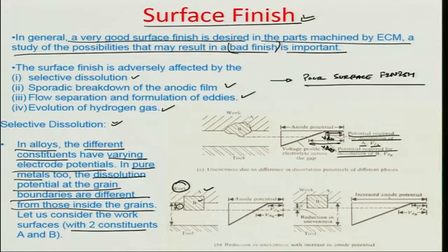So, we would like to presume here that there is an ohmic drop in the electrolyte in between this gap. This is all filled by electrolyte, and there is a straight line ohmic drop, as you can see here, as the voltage changes between the cathode and the anode. It is done in a manner so that VDA, the available potential which would cause the start of the dissolution of the phase A, is available at a surface. But the availability of VDB potential is down underneath somewhere, where the voltage drop results in VDB.